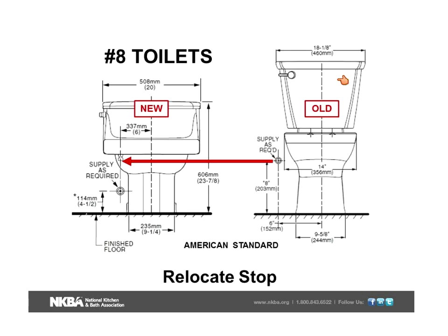Here's another issue you need to be careful of. The homeowner wants to swap out their existing close-coupled or two-piece toilet with a low-profile one-piece toilet. Notice, and this is straight from American Standard, where the rough end is for the valve or stop where the supply will be connected to the tank. Notice where it's suggested. If you follow that right across to the new location, you realize that it's much lower. That means that that stop has to be lowered on the wall.